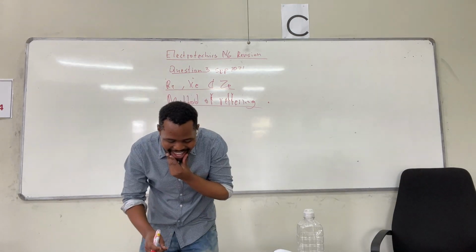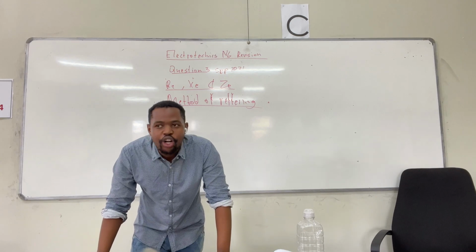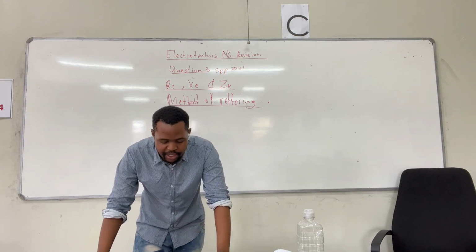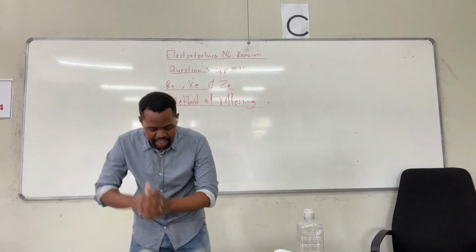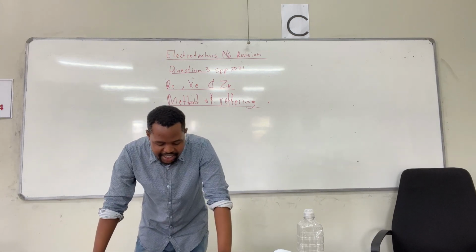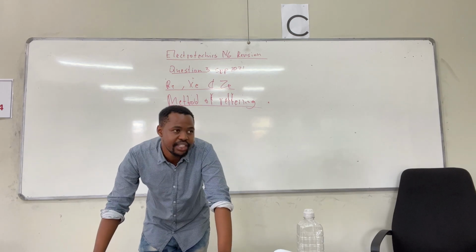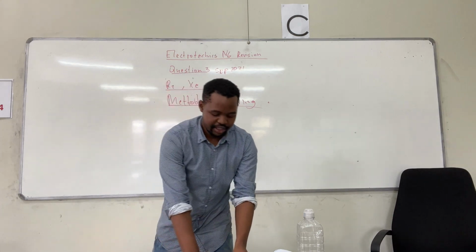These matched windings are called equivalent windings, which have their own resistance, reactance, and impedance. Any value of resistance or reactance taken from one winding to the other is said to be referred. Okay, let's turn to the next page.